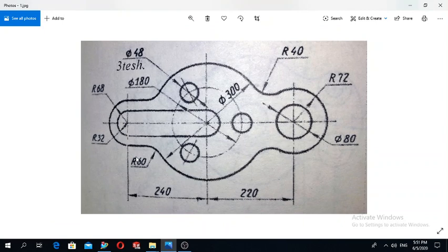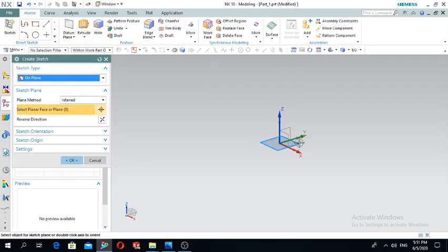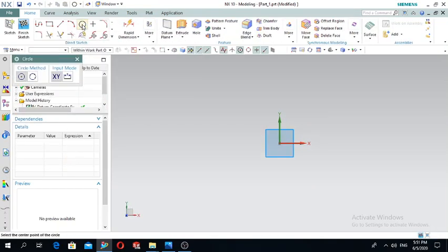First we will draw this project, so you can start as you want, and in this case let's start to draw this big circle with the diameter of 300 millimeters. So sketch, select the XY plane, press OK. Circle from the direct sketch toolbar and use the circle by center method. So draw in the axis of the origin, draw the circle